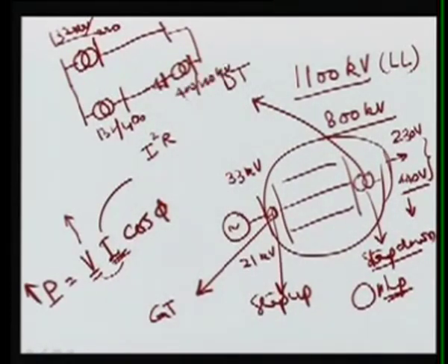So these transformers are called power transformers, and they are used in the transmission system for connecting the different levels of voltages. So you can see here the 132 bus, here the different lines, they are connected with the 220, they are connected with the 400. Again we are using different ratings and different voltage levels of the transformer.